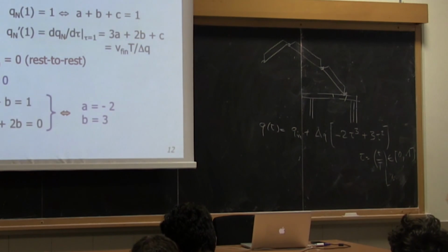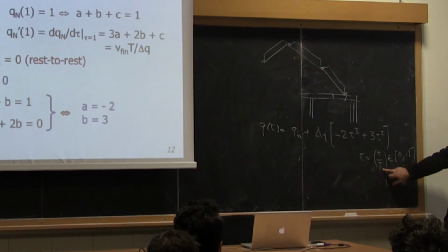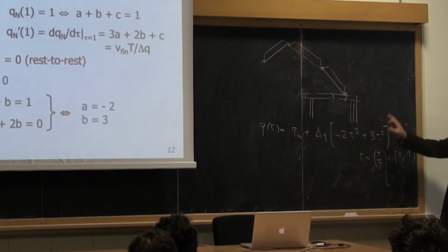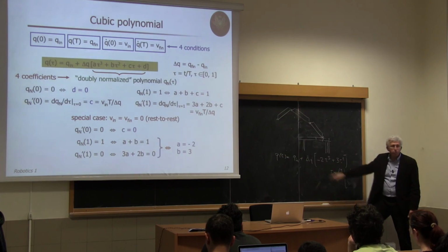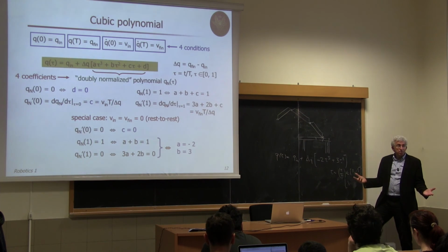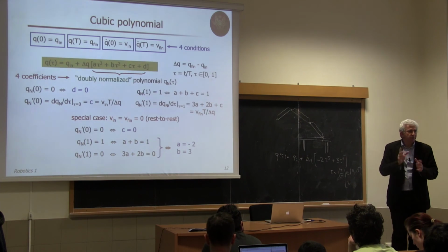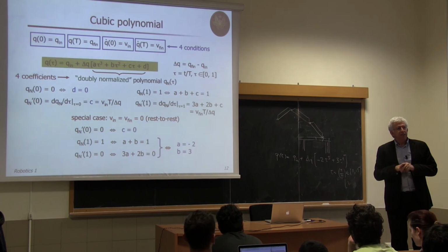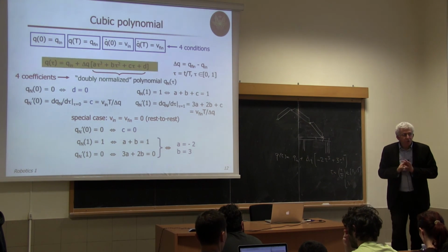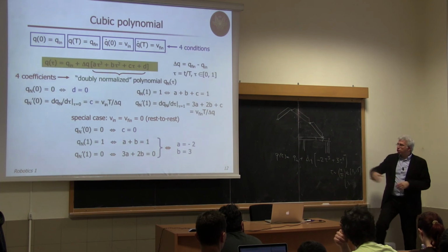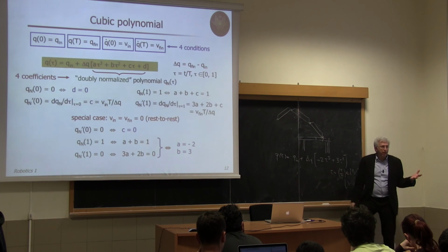Okay? So no matter how much you need to travel, no matter how much time you need to take, this is a rest-to-rest polynomial. It's always like this, with two coefficients which are integers, summing to 1, and of opposite sign. There are nice properties that can be generalized. So don't make the mistake of saying, okay, generate a trajectory which makes 37 degrees in 1.5 seconds.